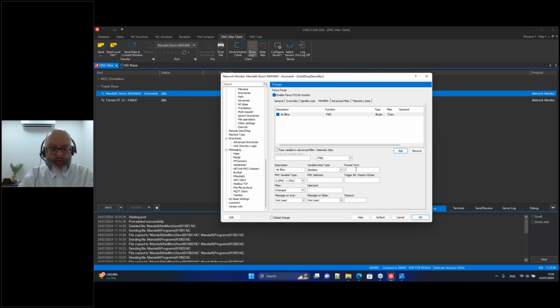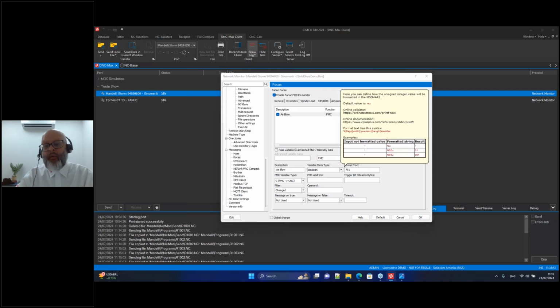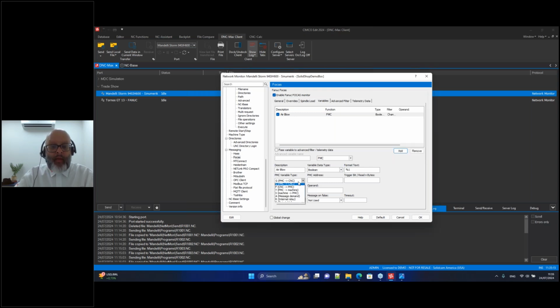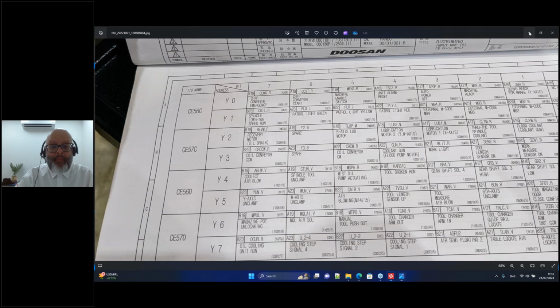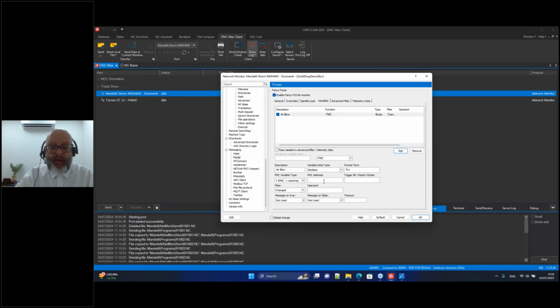So I only go here and say percentage 1. You can click here on the help, and it's going to tell you how to use that field. And now I go here and say it's a Y address. Remember, on the PLC, on the electrical diagram, it says the address is Y5. So it's a Y type address. And I say PMC address is 5.